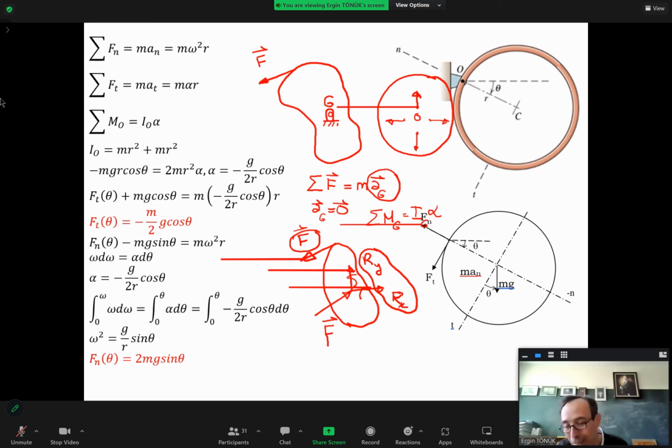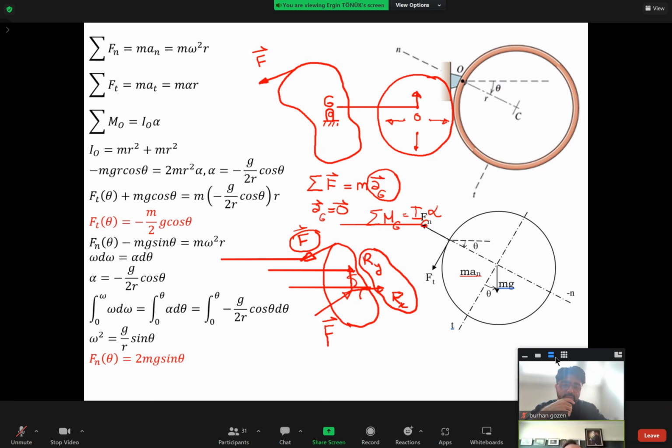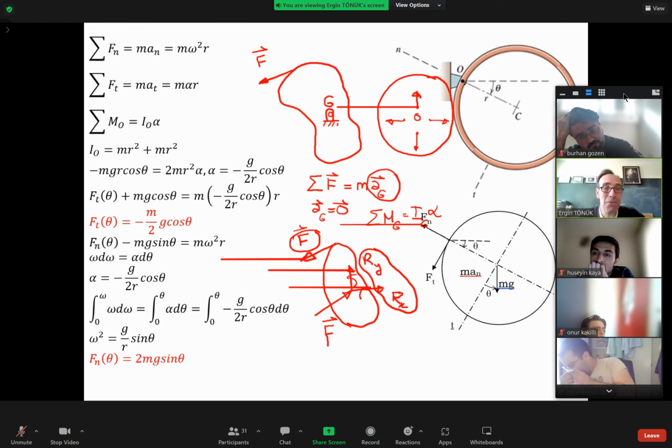And another thing, as you might know, we can't satisfy certain things exactly. For example, when you balance a wheel, you don't exactly bring the mass center to the center of rotation, but you bring it close to it with an acceptable tolerance.